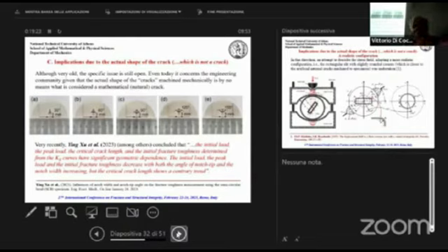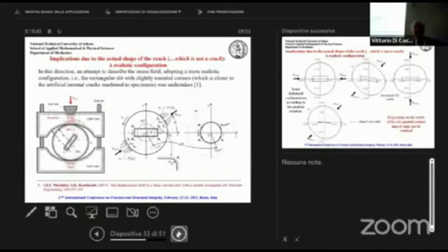We use the standards of ISRM, but as Ying Xu et al. said, if we ignore the actual geometry of the notch and the dimensions of the crack, the result that we obtain could be erroneous. So we undertook an attempt to find the stress field in case a finite disk is loaded and the discontinuity is in the shape of a rectangular notch with rounded corners. Obviously,